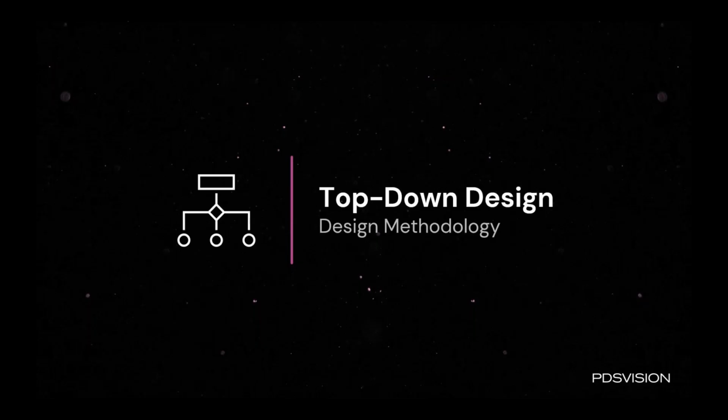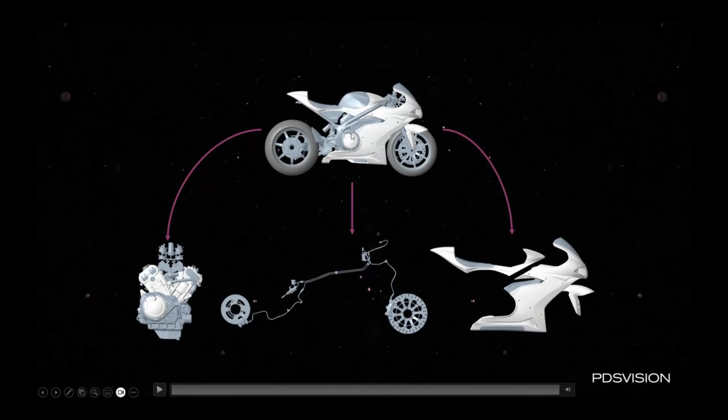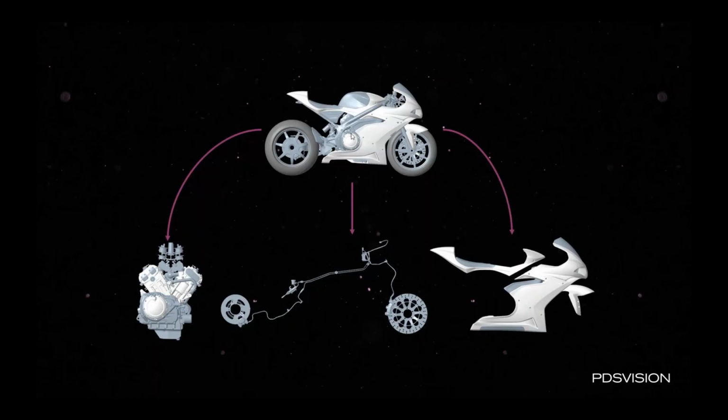You have parts being designed in isolation that don't communicate with each other. Changes can behave unpredictably, and it becomes a bit of a headache to implement those changes because you've got loads of different parts you have to modify. And coordination really becomes more of a challenge. So top-down design flips that on its head. What we do is start off at the top level, at the overall assembly level, and then work our way back down through the model.